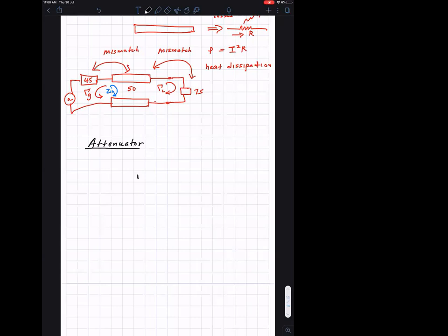Sometimes you use an attenuator to reduce the power to a measuring instrument because the measuring instrument cannot take high power. So you want to attenuate the power so it won't damage the equipment. So P in is 8 dBm. And then P out is what? I'm asking you. If you use a minus 2 dB attenuator,